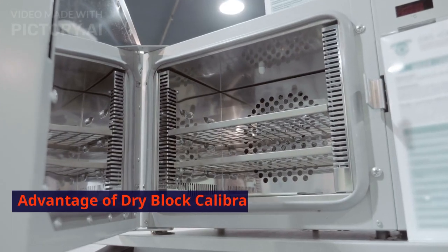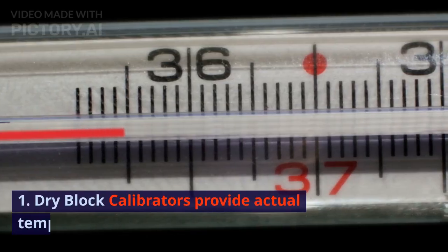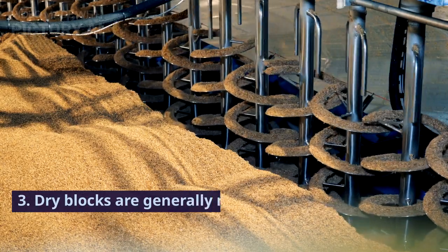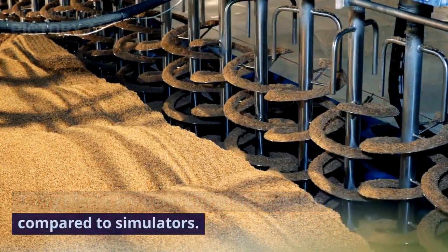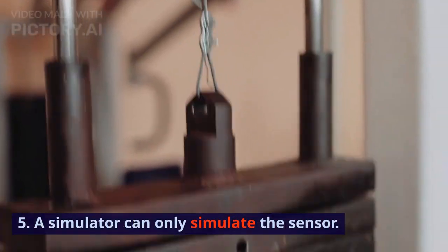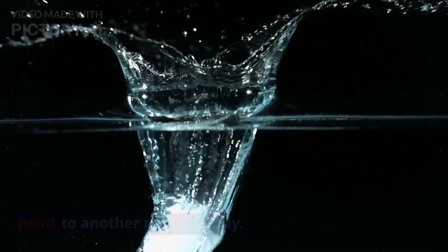Advantages of dry block calibrators over simulators. 1. Dry block calibrators provide actual temperature calibration of the sensor. 2. Minimizes risky sensor errors. 3. Dry blocks are generally more portable compared to simulators. 4. These do not require any kind of fluids. 5. A simulator can only simulate the sensor. 6. Dry blocks move from one test temperature point to another more quickly.